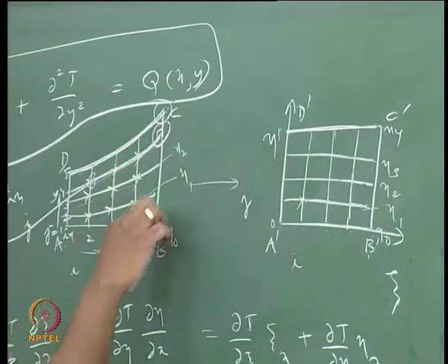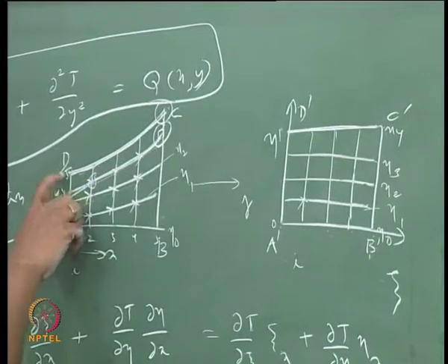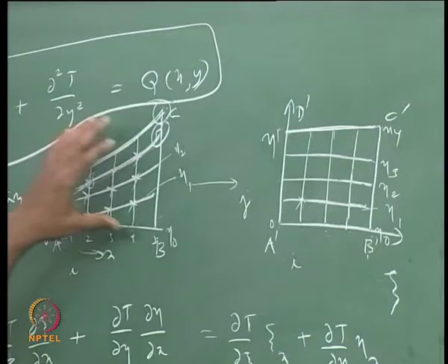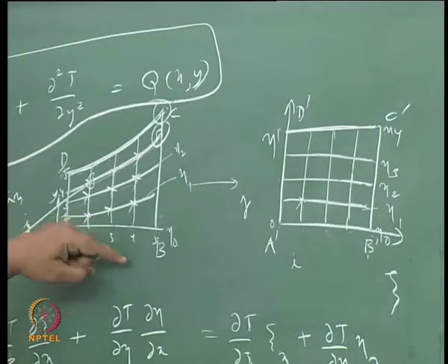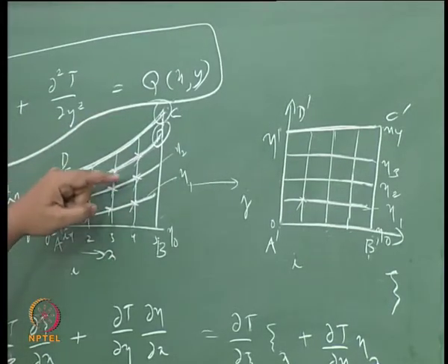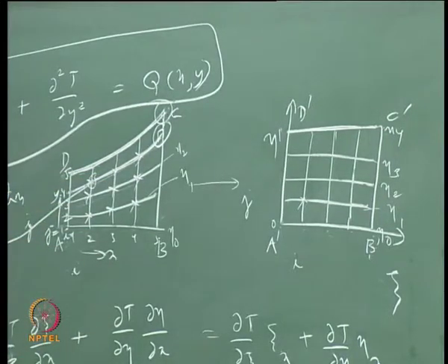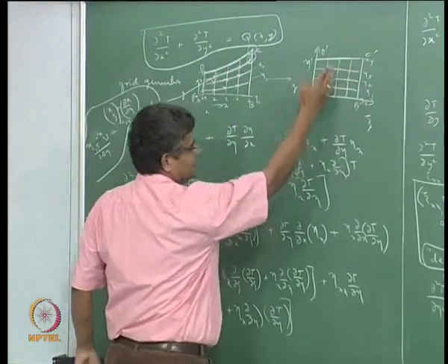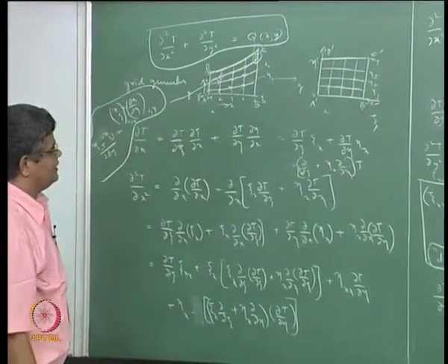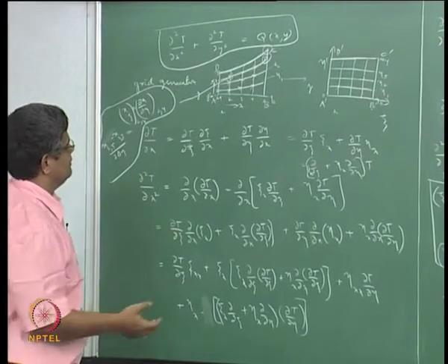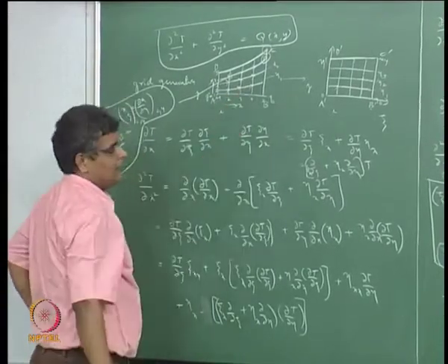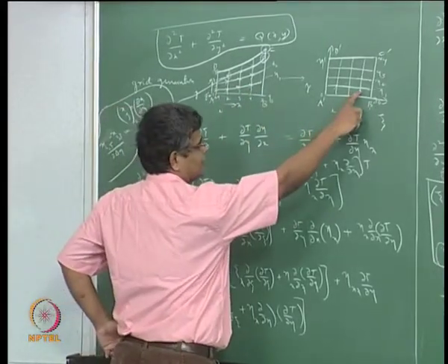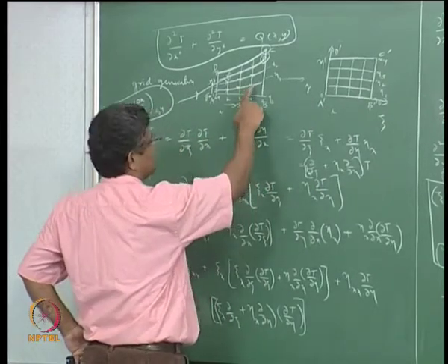And similarly, the points on these things are fixed, and points on these are fixed, points on these are fixed. Now, once we identify the boundary points, then we have to get the interior points such that we have a smooth grid, and then these lines here map onto the constant psi and constant eta lines here. So, based on that we derive all the interior points, that is we find at every ij what is psi i, eta j and what is xi, yj.